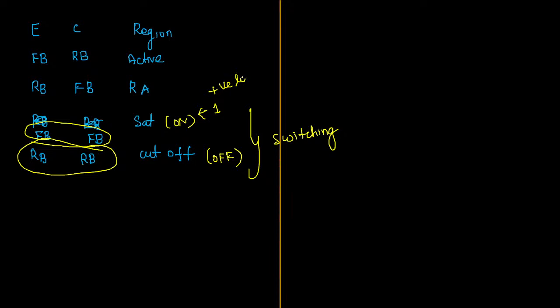There are two types of logic and we will be using only positive logic. If they say that they are using negative logic, that case is very rare. I haven't found any questions in the past 25 years with negative logic, in switching schemes I'm telling. Negative logic means instead of 1 we will be keeping 0. In on state your value will be 0, in off state value will be 1 in negative logic. Negative logic means just opposite to positive logic. Positive logic means in off state value will be 0, in on state value will be 1. That is how we are designing the switching schemes.